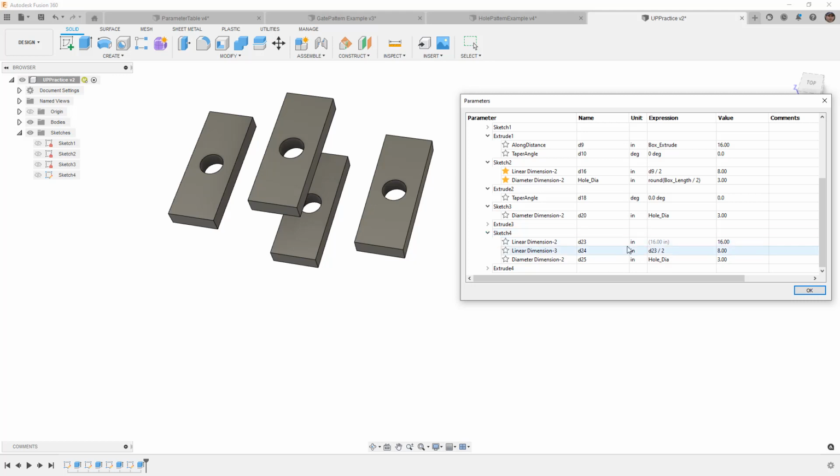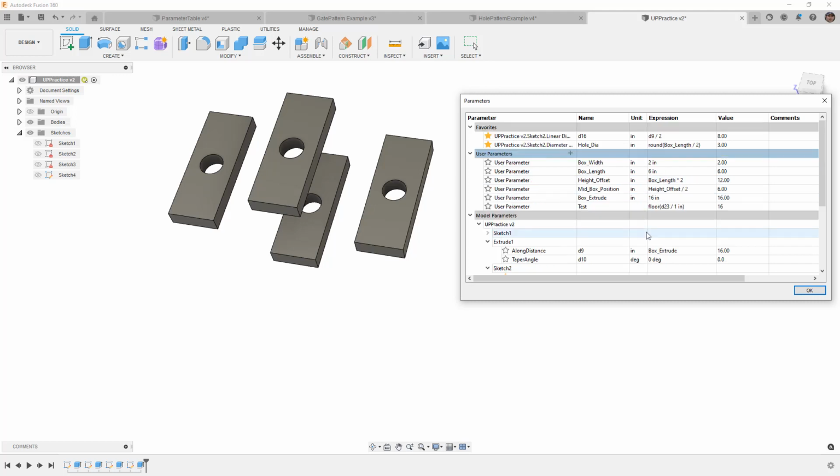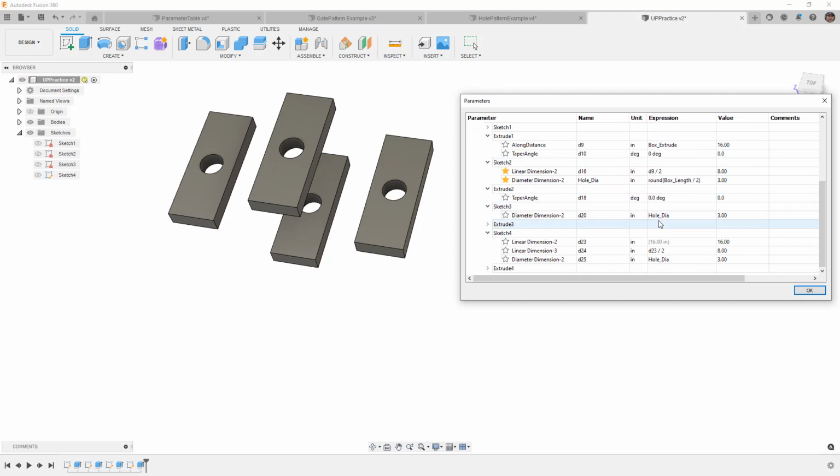And the last option is, again, the limitations with driven dimensions. As you saw, that sketch still appears to be underdefined, even though it is actually fully defined. So that is one downside to using the driven dimension. The other downside is that I found that driven dimensions often don't work inside of these logical operators, these functions like round. So you have to think about that, and I would suggest avoiding using driven dimensions if possible,